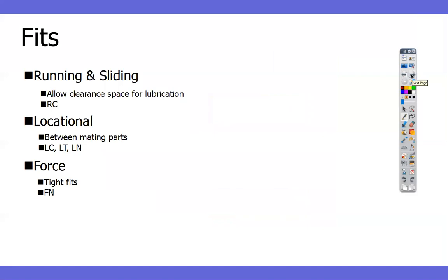So now how do we use tolerances? The most common way is when we're having things fit together somehow, right? If it's the outside of the part, we really don't care about the tolerance that much. That's where it might be 2 decimal places. If it's just air sitting in it, we don't care. Maybe we can drop to 1 place. I mean, it's not going to fit into something. It's off. Who cares?